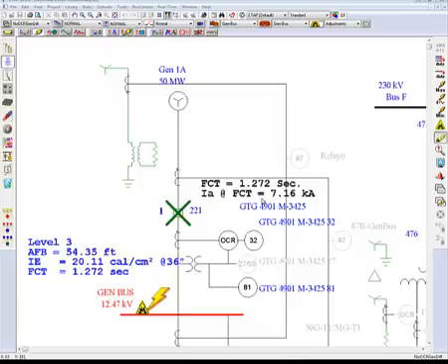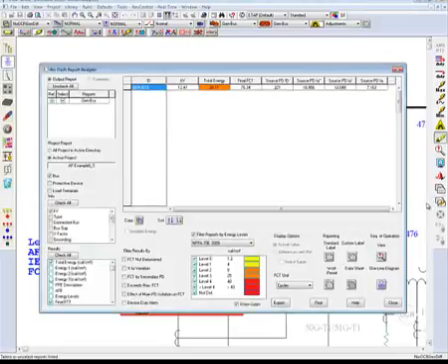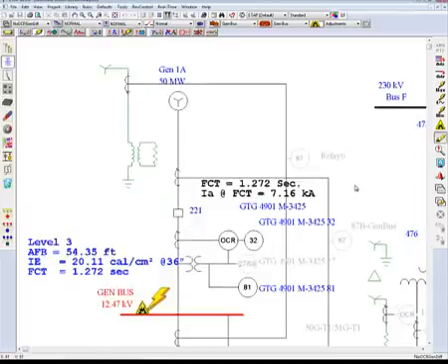You can also verify what current is passing through the device through the arc flash report analyzer. This one seems like it would be the steady state current, and that's what it is, as shown here under the source PDIA column. The second function that the sequence of operation can help with is to visualize the multiple source arc current contributions in your system.